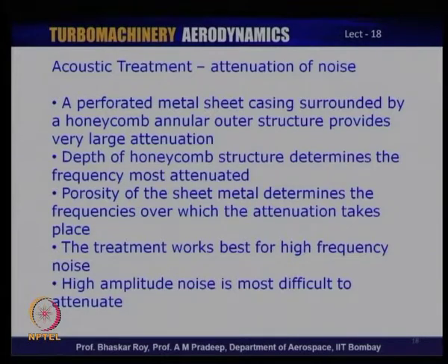The depth of the honeycomb structure determines the frequency which is mostly attenuated or absorbed. So, the honeycomb structure will have to be designed by specialists to absorb noise of certain kinds, so that most of the high pitched noise is indeed absorbed. The porosity of the metal sheet also has to be determined in a manner which actually attenuates certain kinds of noise frequencies.